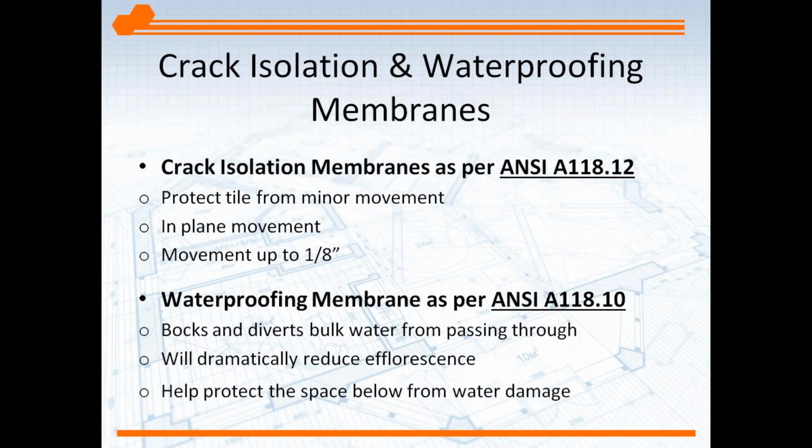ANSI has a standard for those products. You'll see it on the top there. It's ANSI A118.12. So if you have a crack isolation membrane on a project, I would suggest that you certainly want to make sure it meets the ANSI A118.12 standard. In that standard are, again, the ASTMs that govern the movement and the bonding and things like that of that membrane. So you're covered when you have that.